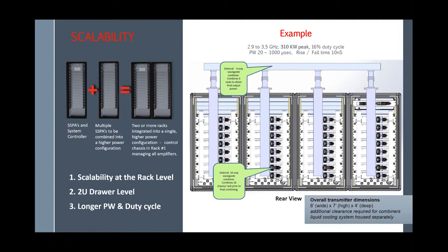The advantage of having a smart amplifier is that I can define profiles, and I can say up to 500 microseconds in certain cases, I operate at full power. Sometimes, in this case the C-band, I can go up to 1 millisecond.